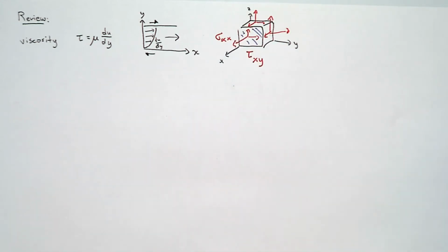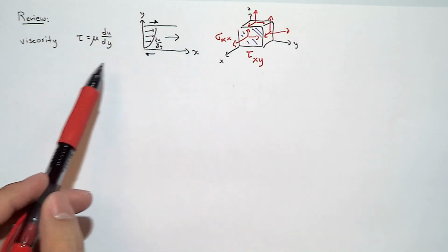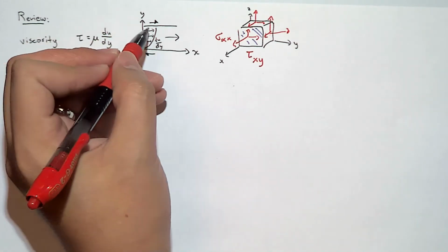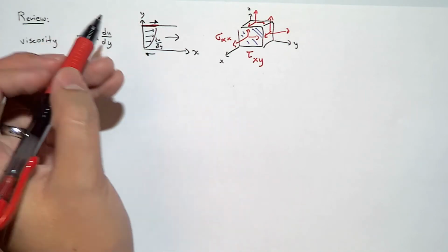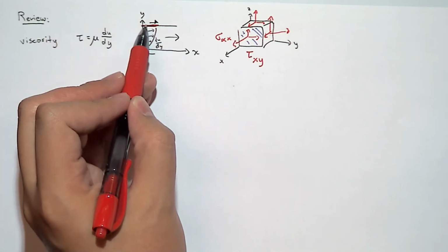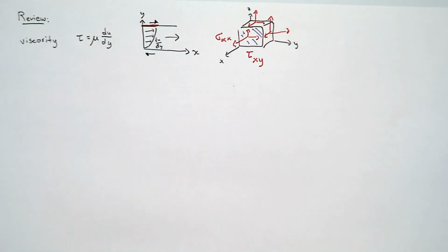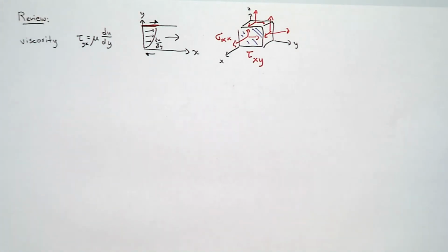So based on that information, I think we can understand that this equation of Newton's law of viscosity for one-dimensional flow really is only giving us one of these stresses, because we're only looking at the stress, in this case, that's acting on the y face, right? This will be my y face because the area vector for this face is normal to the face, so it points in the y direction. In the x direction, that's correct, thank you. So this is actually tau yx.